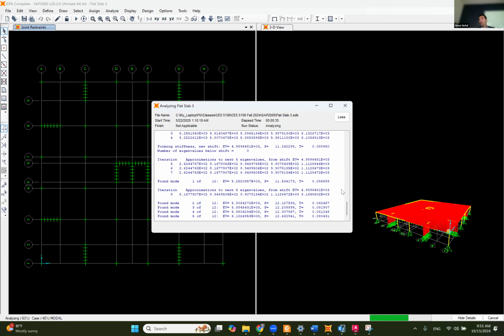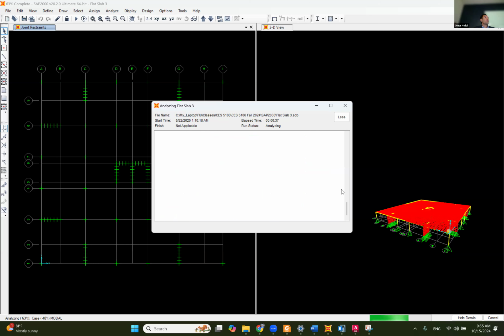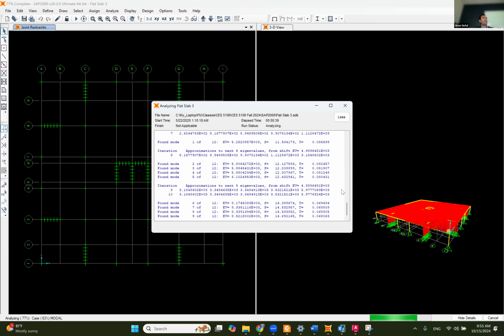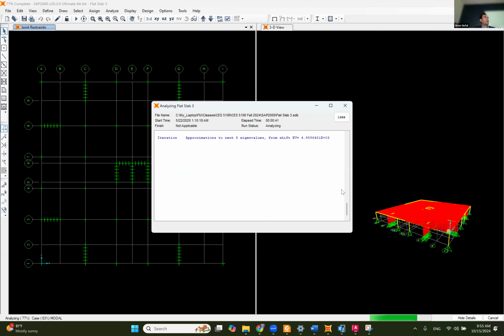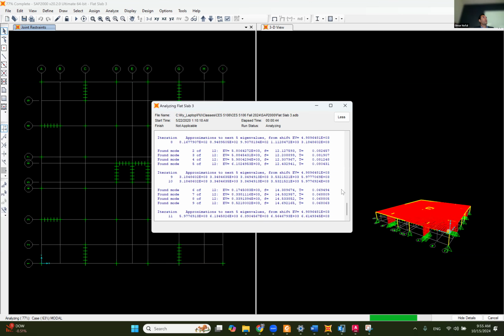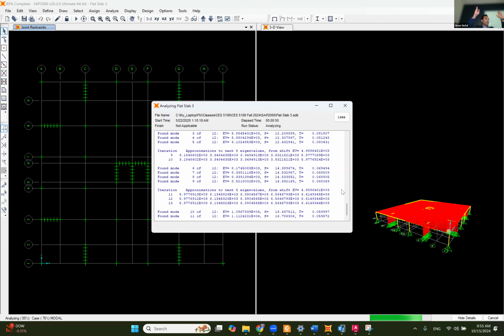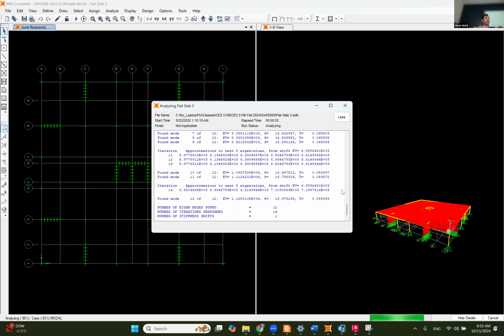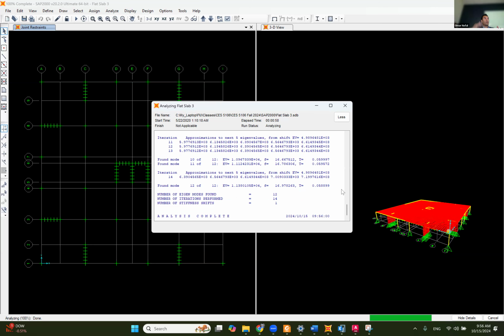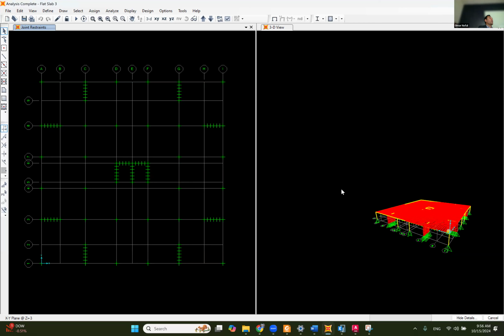Well, that's a good question. Sometimes, if you don't have what they call sliding scaffolding, the first thing is that you have your shear walls and the reinforcement is coming out, and then you put the concrete and make the concrete of the slab and the shear wall together, with the reinforcement of the slab going on top, so they are all as one element. I mean, they are not one element, but they are connected together.